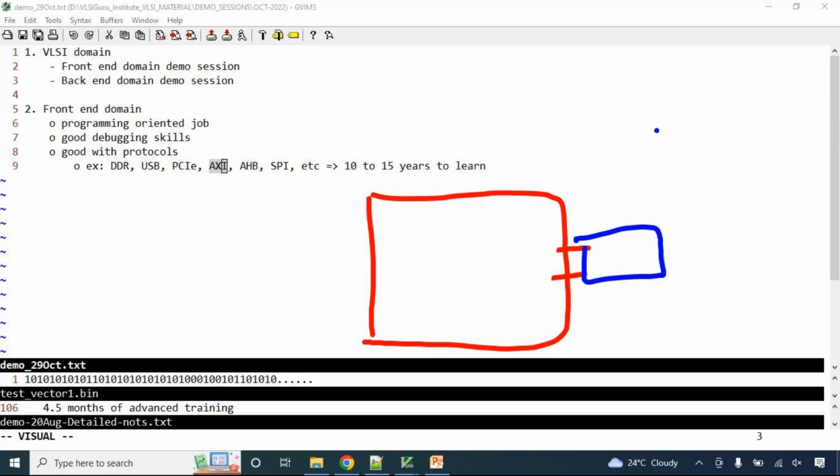Assume we did something and we are able to connect those wires also. So we did soldering. We took small copper wires and soldered them. Will it work? No. Why? Because the functionality of the SD card is meant to work with the SD card protocol. There will be specific protocol rules for how the information will come, how the packet will come, how to respond. Even the one sending will be sending USB packets. There will be USB frames, token packets, data packets, handshake packets, which the SD card will not understand. That guideline of how it happens is called the USB protocol.